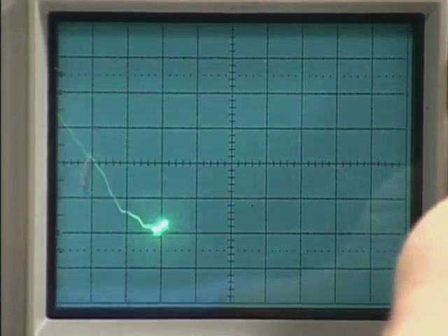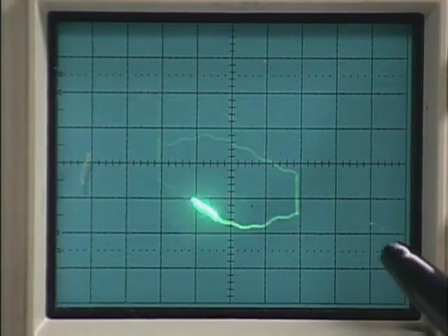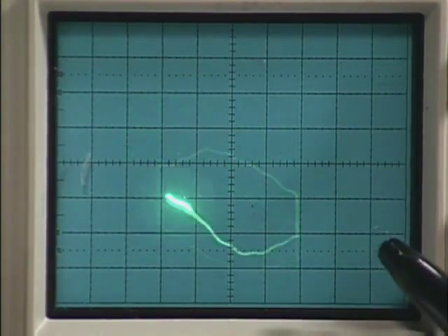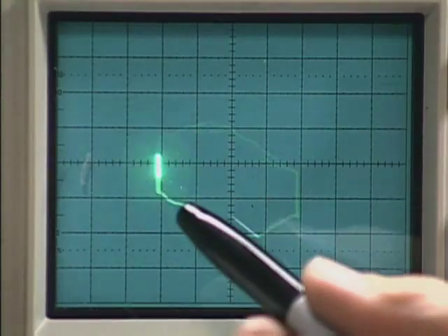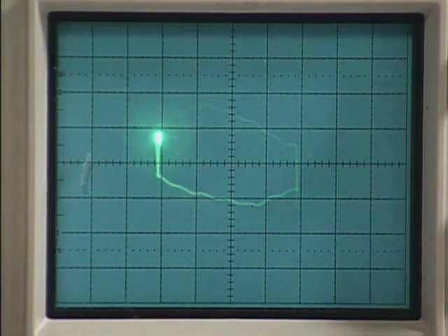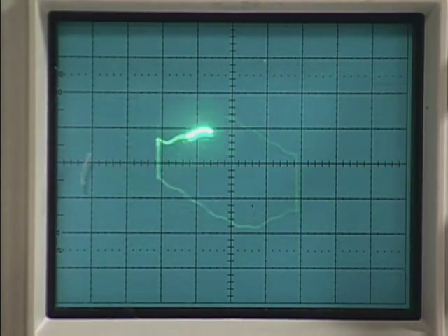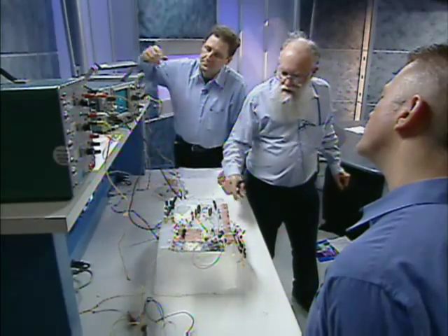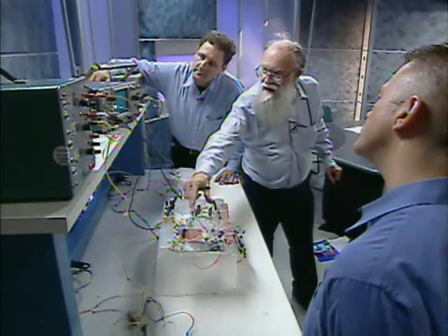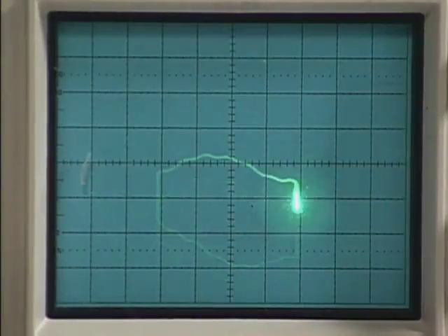And that's a conventional display. Now this is an XY plot. You're just looking at what we're pumping into that bridge. Now, when we put this into XY, we have a signal that's wobbling around a little bit, but it is well behaved. If this was sloping left and right, we'd have a lousy balance of offset. If we were sloping this way, we'd have terrible errors. We can put this in, and it jumps all the way because it's so sensitive. It's measuring the temperature, we're talking about just 1 part per million resolution.